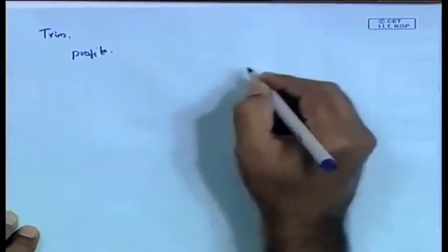The same way as you see heeling, that is, we have the KG, KB, then LCB, KG, KB, etc., and the metacenter, the new position B phi, the metacenter, we discussed all that, and that is all seen through a transverse direction. That is, the view is from the transverse direction, that is, if the ship is like this, we are seeing it from here. So, it is a transverse view. Now, suppose we see the same thing in a longitudinal direction, like this. This we usually call a profile. So, we are seeing a ship like this.